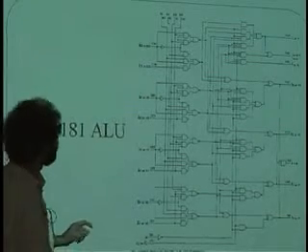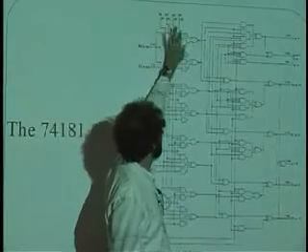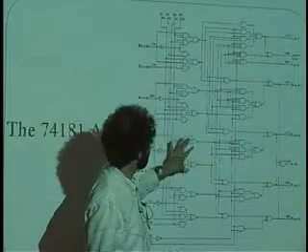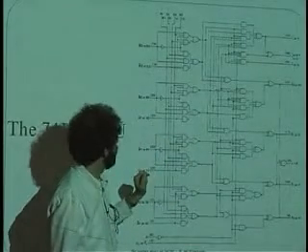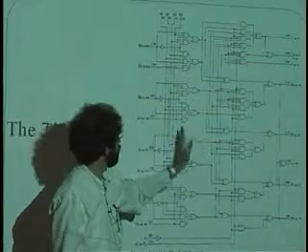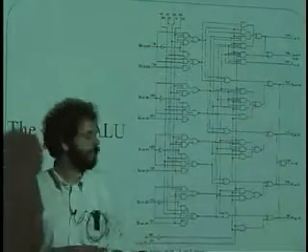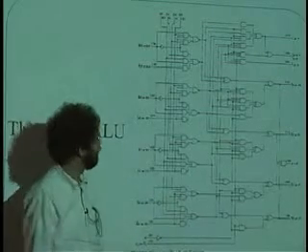And it turns out that if I just fix this code with the code for add, what you would find is that the G and the P that gets generated by the logic function right here, and notice this is a sum of products form, here's the OR gates, here's the AND gates, here's the NOT, right? Each of these things will in fact be the generator for doing G and P.